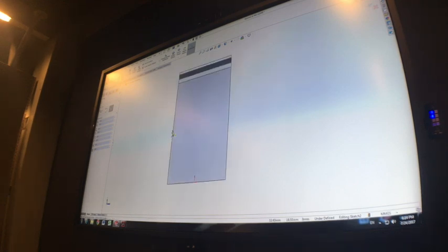And what I'm going to do, how the 3-point arc works, you click once, you drag, you click again, you drag, and you drop. Okay, so that's how the 3-point works. When I hover on this shape and on this end line, you see this little yellow point that comes up on the line? That there is signifying the middle point of that line.